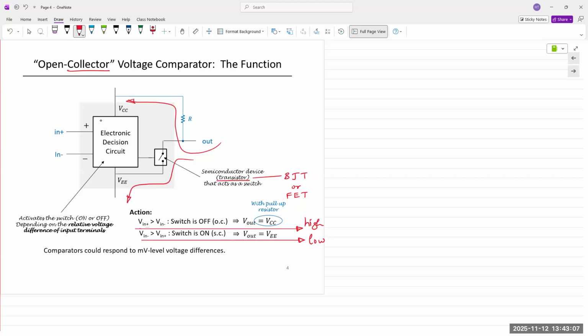Similar to op amps, comparators can also have dual power supplies. It's not always necessary, but on lab benches and installed equipment, you would be able to find dual power supply rails. One thing on the previous slide that I didn't mention is that op amps and comparators look very similar. The transition symbol is not always presented. In fact, I can't remember the last time I saw a comparator with the transition symbol.